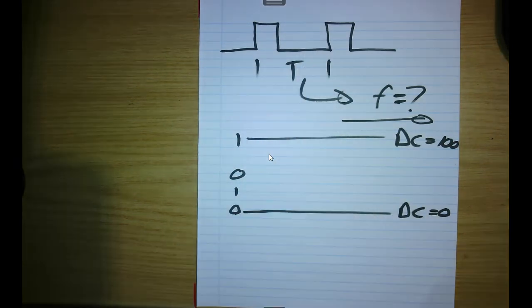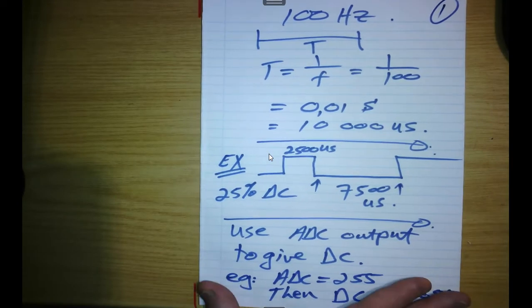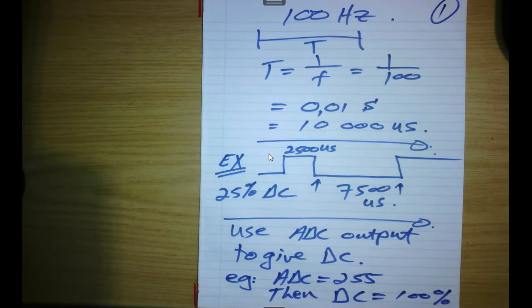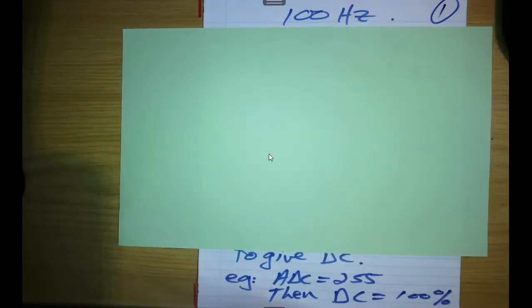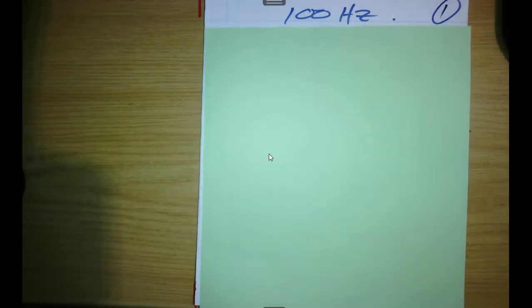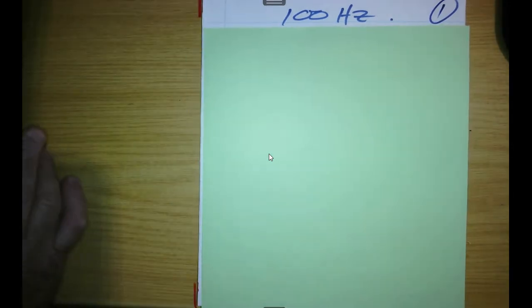So what I'm going to do with this example of mine is explain to you how to do pulse width modulation by making use of a 100 hertz pulse. Now, I want to do this example making use of the 8051, and if you go to higher frequencies like 10K, then this microcontroller is becoming too slow. So if you really want to make use of high frequencies, you must use a faster microcontroller like the AVR.